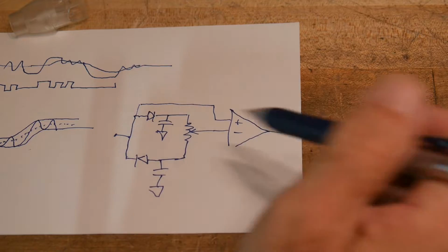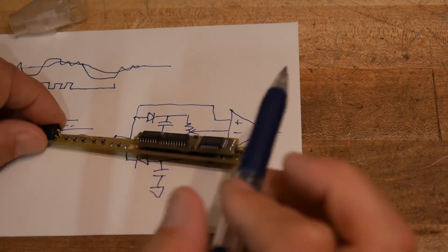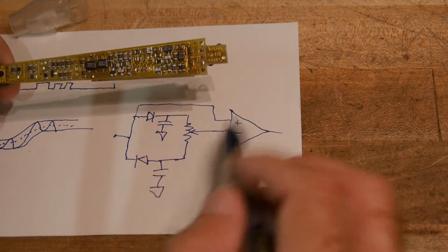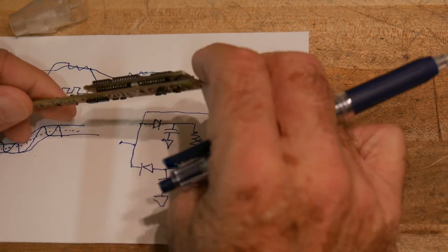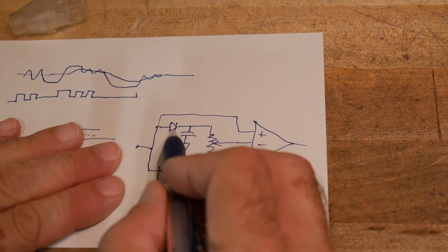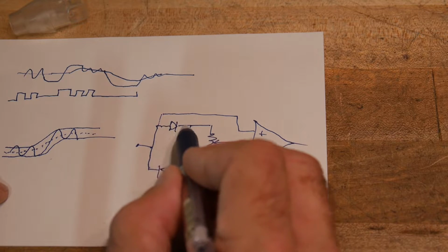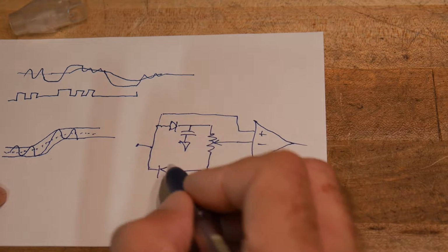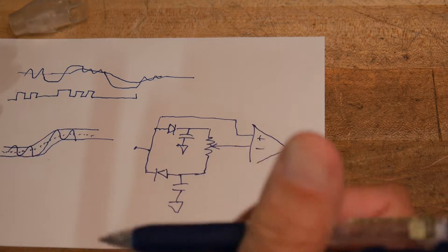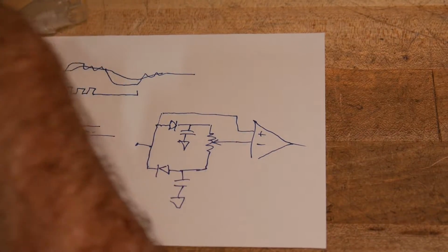So this is sort of the idea of all of the circuitry here. It's a little bit fancier here, but this is kind of the basic idea. We'll just kind of stick with that. So one of the things that is a problem with peak detectors is you're losing all this signal. You're losing 0.6 volts going through these diodes. Maybe if you made them Schottky diodes, you're only losing 0.3 volts, but you don't want to lose any voltage at all.